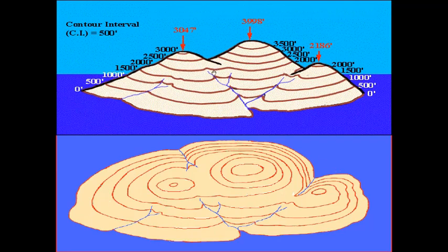And if you don't have this, like if you're watching from the top, a satellite image, then you won't be able to decipher that you have three distinct hills. But once you have the contour map, which is also from the top, just by looking at the map, you'll know whether you have three valleys or three hills. And if you write down the index contours or the contour values along with the map, then you quickly get an idea what the land basically is.